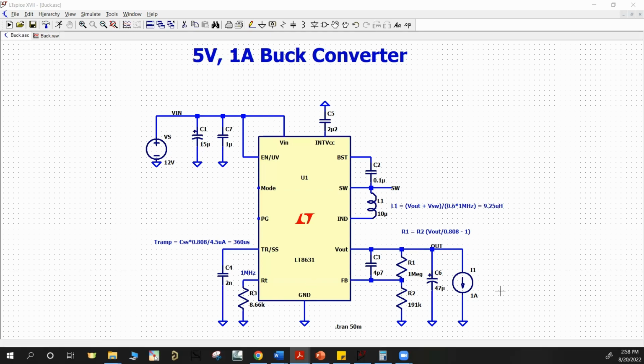So in some cases, we are PWMing an LED or some sort of load by switching this enable pin high and low. Switching this whole switcher on and off does create a lot of ringing, but by introducing some soft start, in this case following this equation, we can control how fast that turn on can be. It really depends on the application.